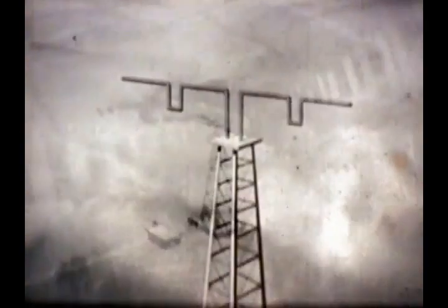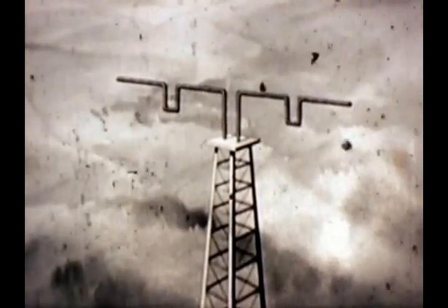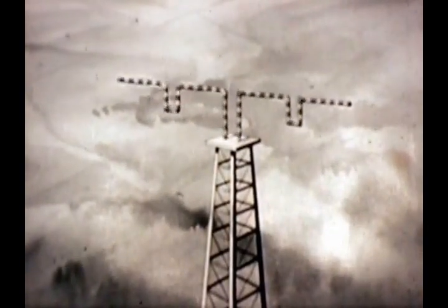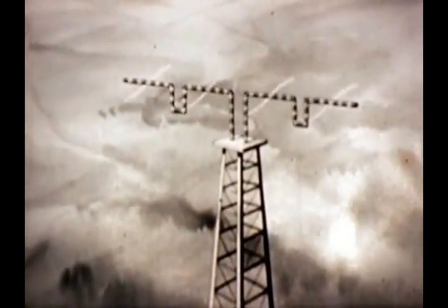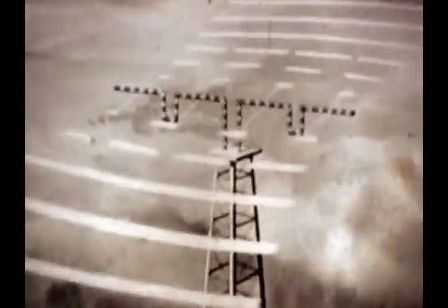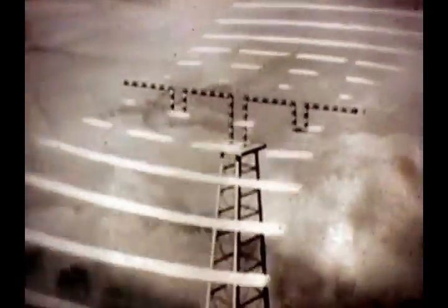Generally, this antenna is stationary. Physically, it can be quite small when very high-frequency channels are planned. The collinear array has two or more elements on a common axis. These elements are a half wave in length. They receive electrical signals of equal strength fed in phase. Maximum energy radiates from the center of the elements, with the strength gradually dropping to zero at the element tips. The same transmission takes place on all sides of all elements.